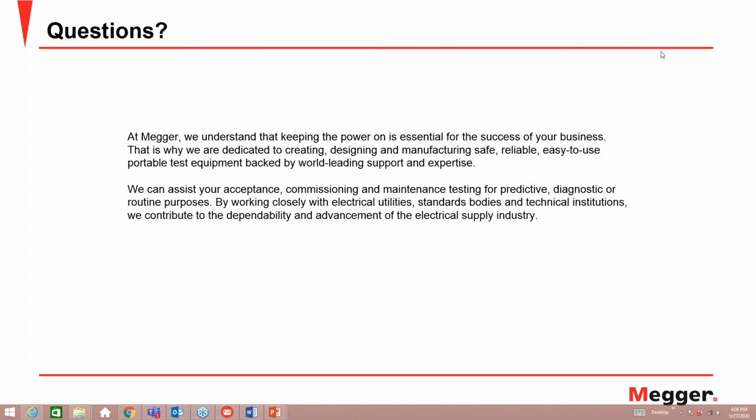As you know, with this type of batteries, VRLA, you cannot replenish the electrolyte. You don't actually have the possibility of checking even the level of electrolyte. So the general recommendation is that you make sure you check with the specific manufacturer of the battery if you have this type of VRLA batteries. The reason is, again, because you cannot check or replenish the electrolyte, you run the possibility of drying out the electrolyte.